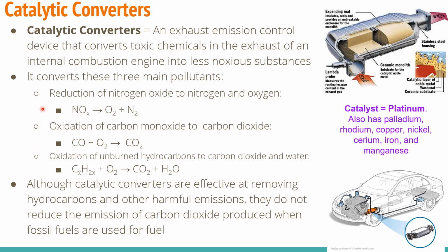The first one is the reduction of nitrogen oxide to nitrogen and oxygen. So if I have nitrogen oxides, this NOx, the catalytic converter converts this NOx, one of the criteria air pollutants, into oxygen, which we like, and nitrogen, which we like. Nitrogen's like 78% of air.